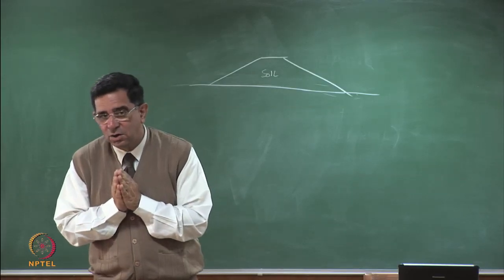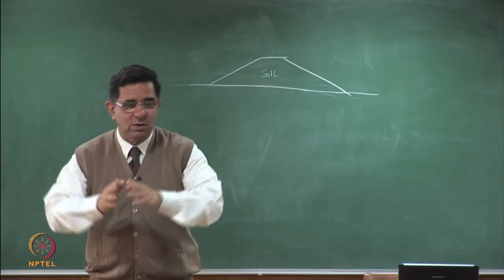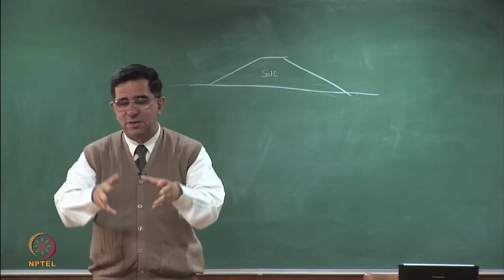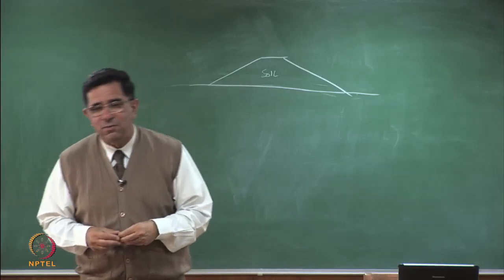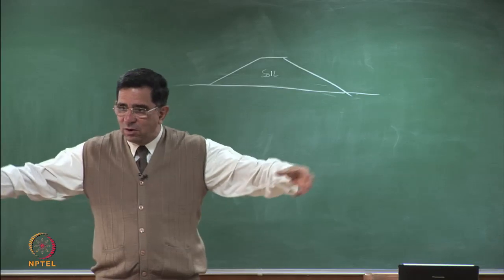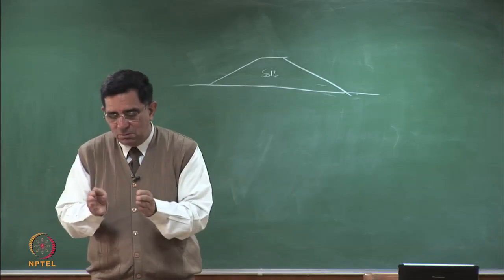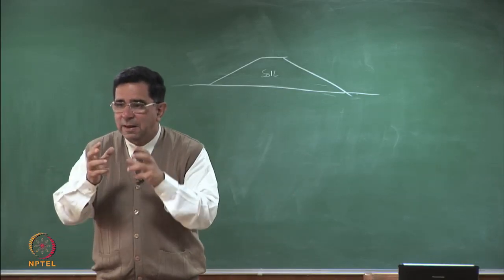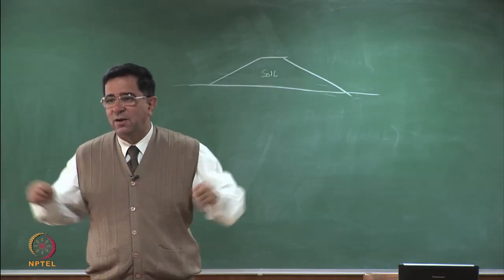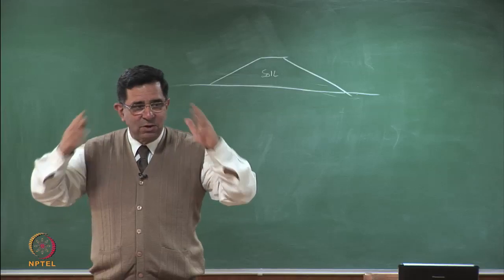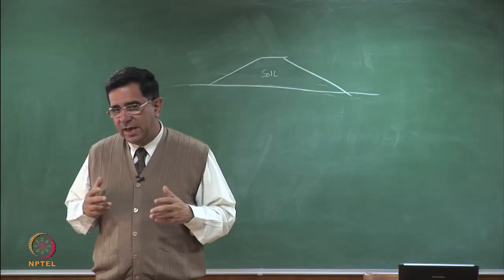For geo? We are not doing geotextile, sorry. We are just taking waste and trying to find out what phi dash. No, fibrous material. Geotextile means a roll, the length is pretty long. Fibrous material means small fibers, so they behave like random fibers. They don't behave like a long fiber. So my question is, what kind of phi dash should you expect?